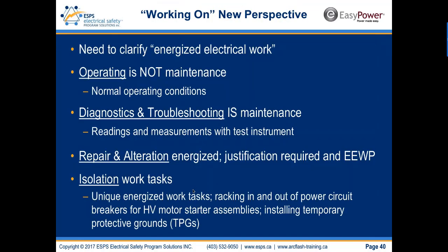So here's my new classification for working on. I've added operating and isolation. So operating is not maintenance. Operating energized electrical equipment is not maintenance, and under normal operating conditions, no arc flash or shock PPE is required to operate energized electrical equipment.